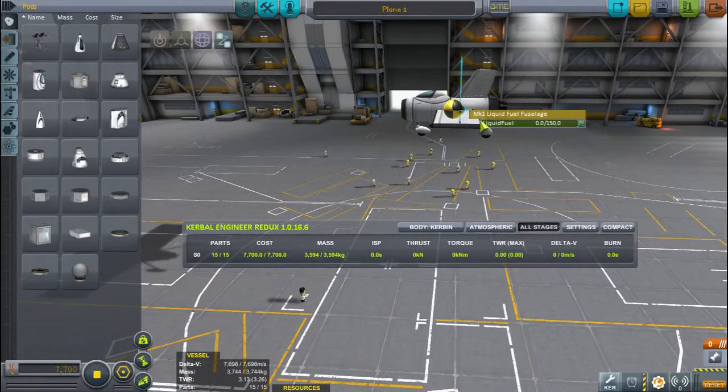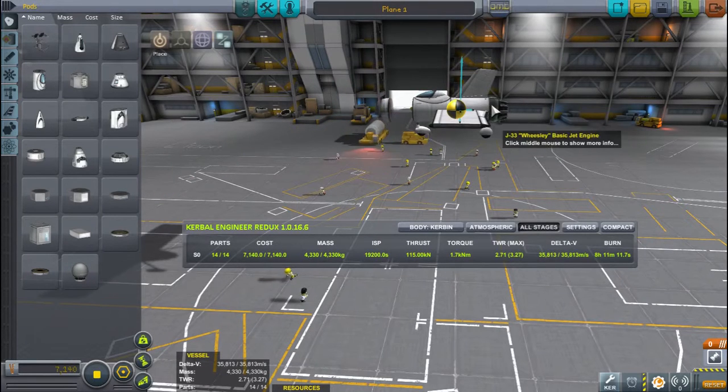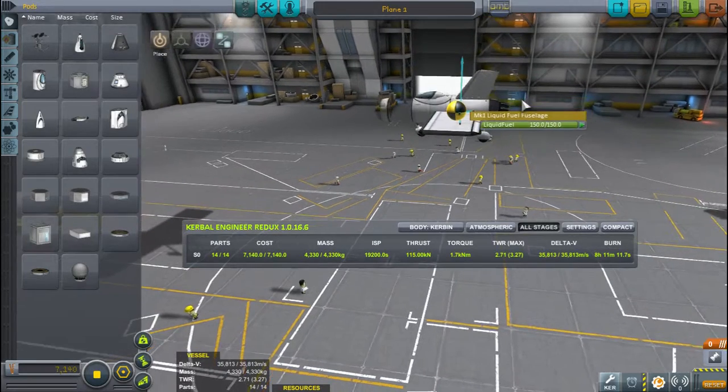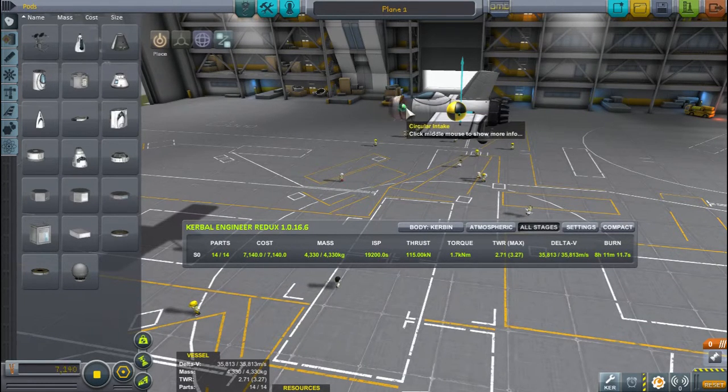Sometimes, probably because we have this air intake, you'll be lucky and it'll move forward and it won't cause much control loss. You take this guy off, and unfortunately, what could happen instead, because of the positioning of this engine, is with enough mass, your center of mass will actually move backwards and cause you to lose control.